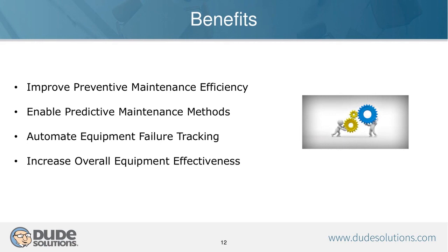So the easiest implementation of a PM schedule in most systems today would be to put them on a recurring calendar event and then have the system generate that event or generate that work order, and you go out and perform the restorative or, for example, the replacing or reconditioning of the components to run more effectively and with high reliability.